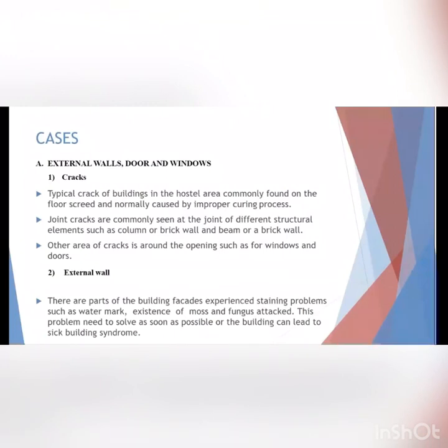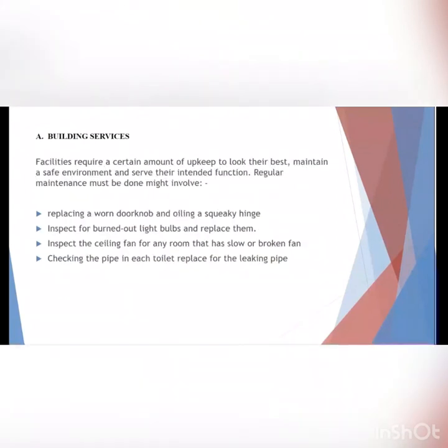So secondly, the external wall. Most of the finished buildings are plaster and paint, so it's common to see staining problems such as watermark existence and moss and fungus attack. So this problem needs to be solved as soon as possible, or the building can lead to sick building syndrome. So the next case